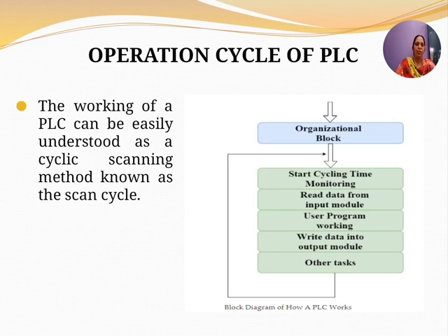As I told you, what does it do? It takes information input from the input devices or the field devices. After taking the information from the input devices, the programming is done using a technique called ladder logic, which allows a sequence of logic actions to be set up, interlinked and timed. And after that the output is driven. So the PLC can drive analog output or digital output devices.